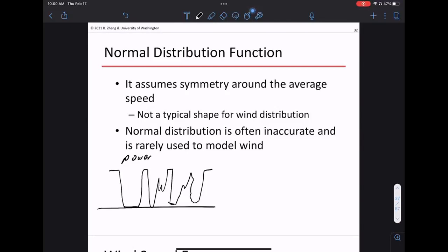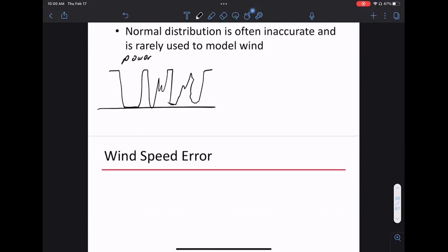As I predict tomorrow's power, I say it's 5 megawatts. What is the spread around my prediction? What is the deviation around my prediction? That is the distribution we typically look at. We never go in without predicting a nominal value. This error distribution is typically pretty close to Gaussian, and that's a nice thing about it.